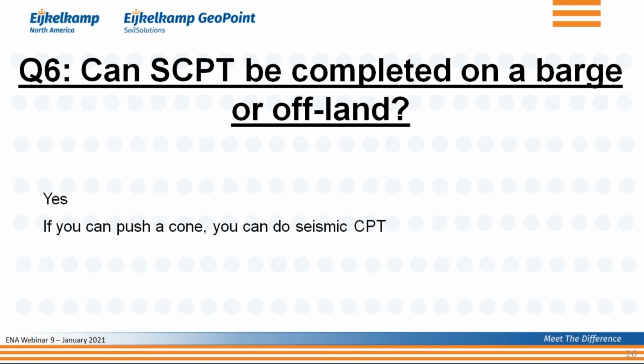All you do then is you lower the seismic hammer to the waterbed, and then you are in good shape. So it's not really whether you can do the seismic part, it's more whether you can do the CPT. And if the answer is yes, then seismic CPT is possible as well.